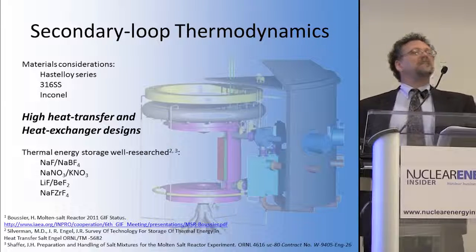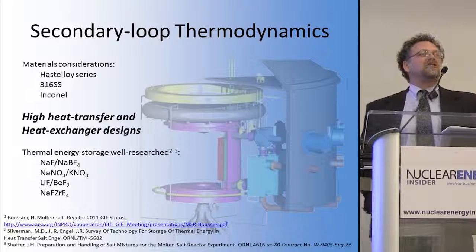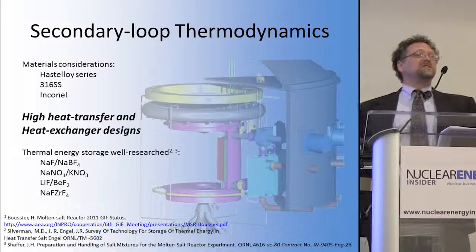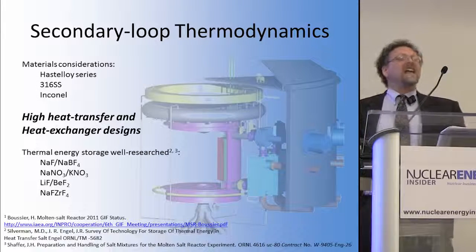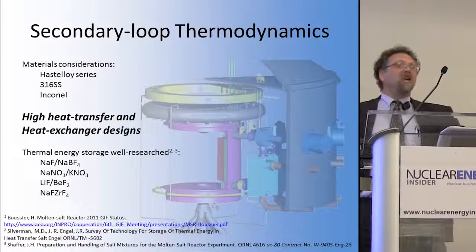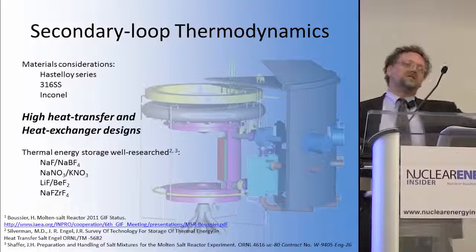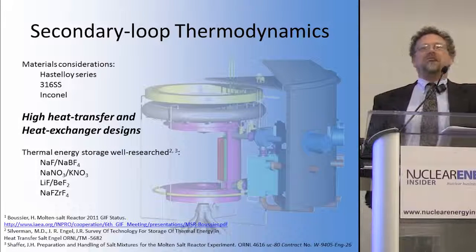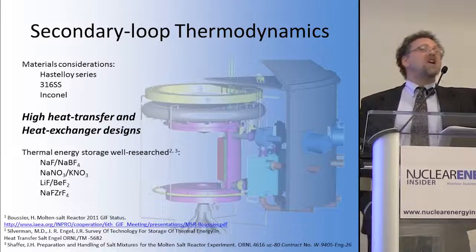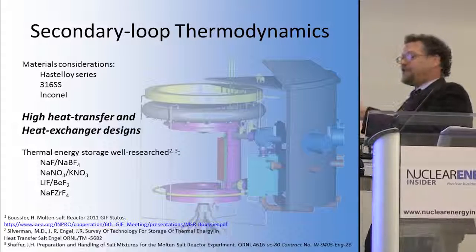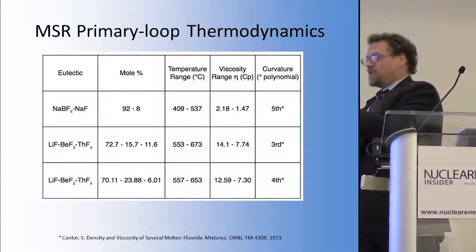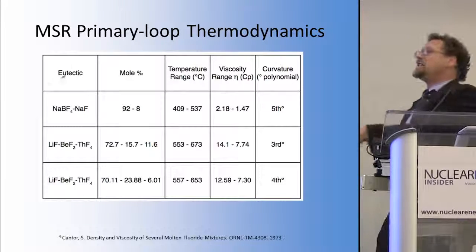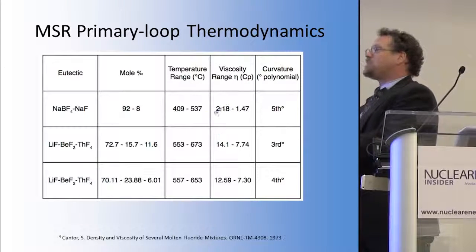But to the best of my knowledge, nobody at all has addressed the very, very different geometries and materials considerations there are going to be if you want to go make a lot of money by just doing chemistry. In other words, using an SMR or a molten salt reactor as a purely thermal platform, not producing 1 kilowatt hour. Nobody's talked about that. And the fact that these viscosities change so dramatically, and a choice of salt is incredibly important, right?